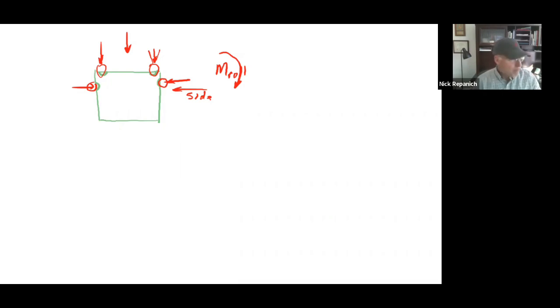And here's one. This would be a size 25 bearing. So just as a reference, here are 2 bearings of similar size. Here's the square rail or the linear guide. This is an old THK one. This is an SR something, probably an SR 25, because this is 1 inch. And here is the round rail. This handled 50 pounds because it was point contact to point contact of the ball bearing on the round steel rail. This one is radius groove. This one's probably about 3,000 pounds and still has a coefficient of friction of 0.003.